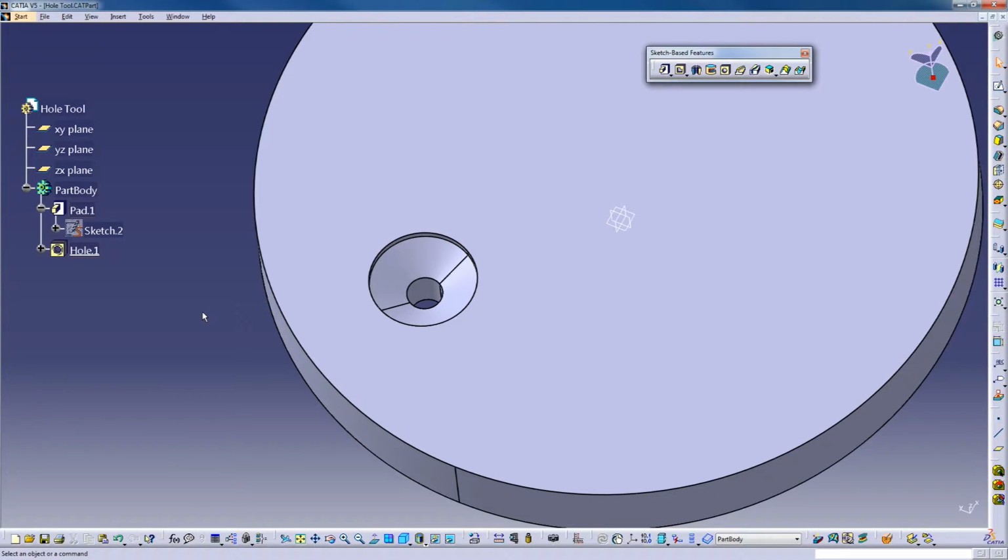They say that because they have 4.5 millimeter drills. When actually, if you look at the best possible fit, you might determine that if we make the hole 4.435, let's say, millimeters, we'll have just a little bit better fit, or undersize, or whatever.